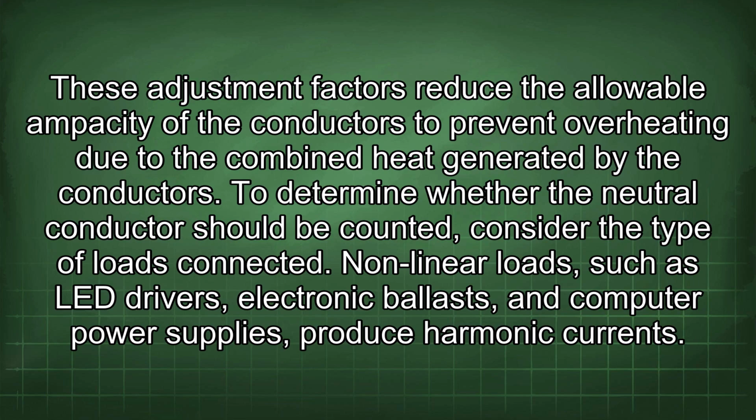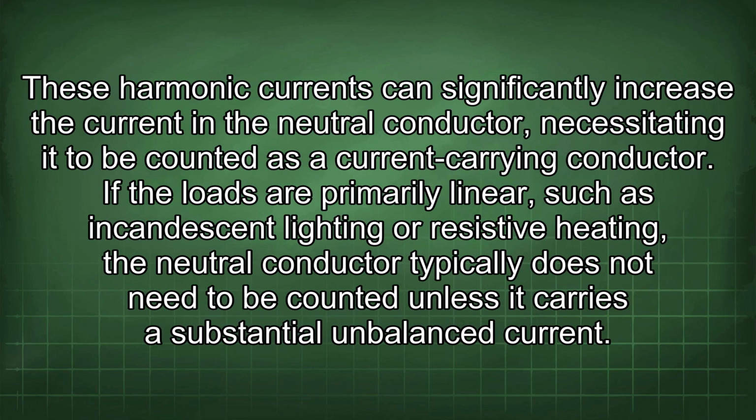Nonlinear loads, such as LED drivers, electronic ballasts, and computer power supplies, produce harmonic currents. These harmonic currents can significantly increase the current in the neutral conductor, necessitating it to be counted as a current-carrying conductor. If the loads are primarily linear, such as incandescent lighting or resistive heating, the neutral conductor typically does not need to be counted unless it carries a substantial unbalanced current.